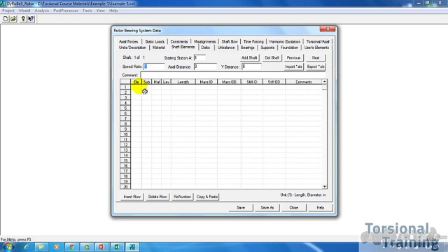So without much further ado, under the element column right here, click there and hit element number 1. So this is the first element, so it'll be element number 1, and under sub, type in 1 as well. Now what the sub is, for very long rotors, for very big models, it's very useful to use sub elements because it helps with reducing the computation time. In our particular case, since we're building one element, it doesn't matter, so you just keep one sub element.